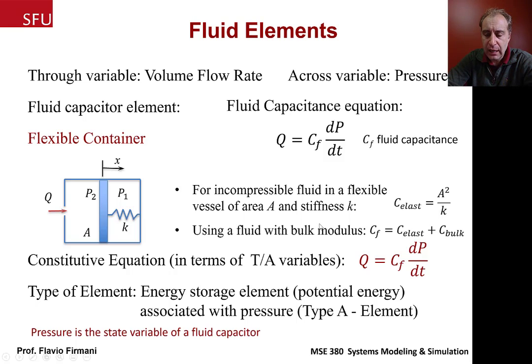Now, in class on Wednesday, we're actually going to derive this equation. So we're going to start combining two different domains, the mechanical domain with the fluid domain, and we're going to derive this relationship that we have here. And again, the constitutive equation is this one, and this is still an energy storage element where pressure is the state variable associated to this element.